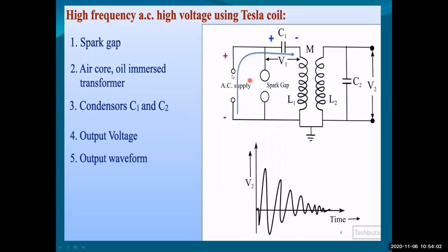Again, try to concentrate by using the figures. You can easily understand from the diagrams. First, by using a high voltage supply, a high voltage transformer, we have to charge the capacitor. In this manner, by arranging the sphere gap distance, the gap acts as an open switch. During that, the capacitor charges to very high voltages in the range of 2 kilovolts to 30 kilovolts. That is the starting condition.